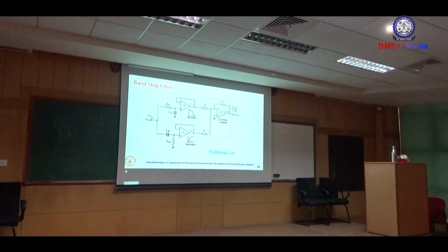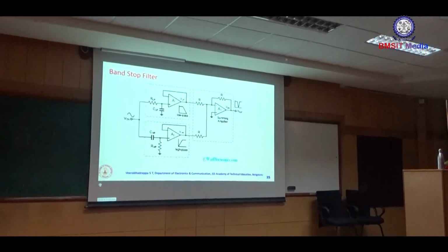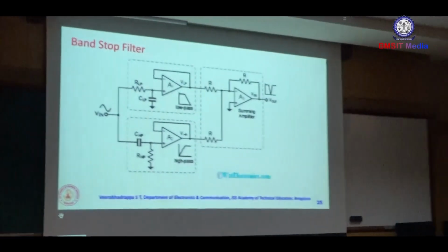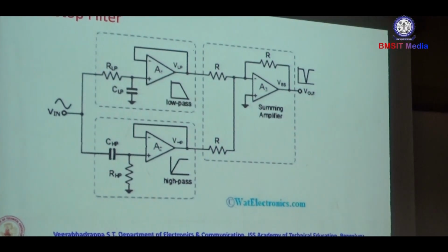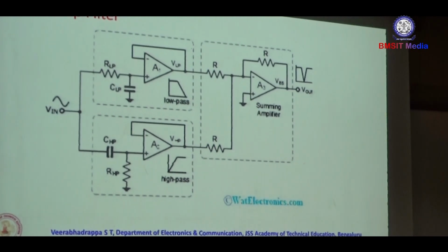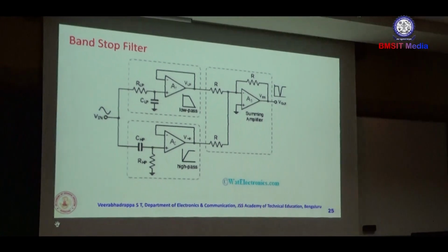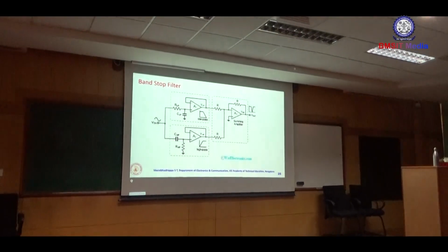Normally see that there is a difference here. When you design a band pass filter, use a cascade. But that same principle does not work in band reject filters. There you add the two signals: the response of a low pass filter and the response of a high pass filter are added together to get the band reject filter. But you cannot do cascading that. What is the effect?